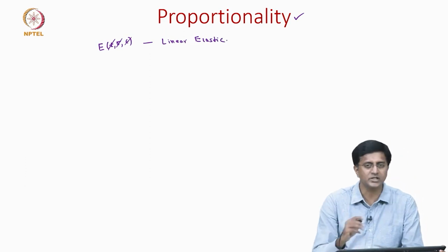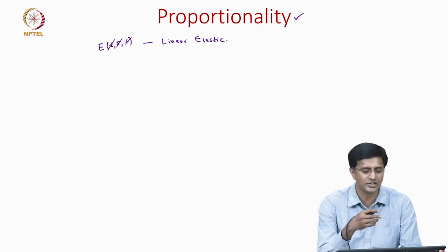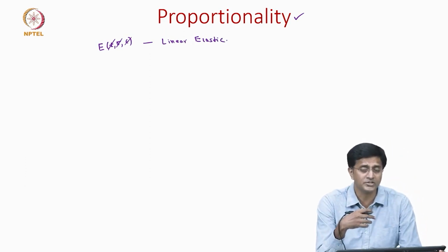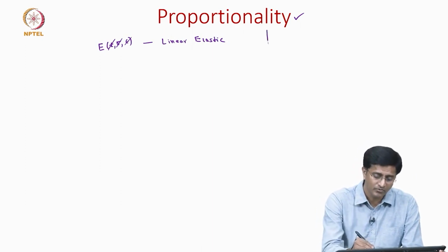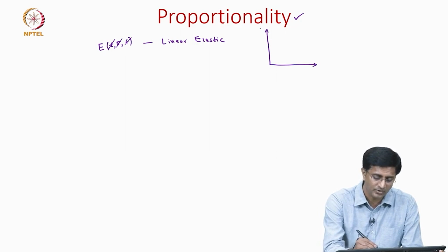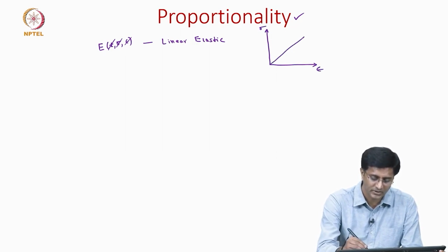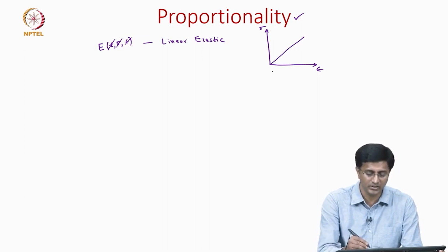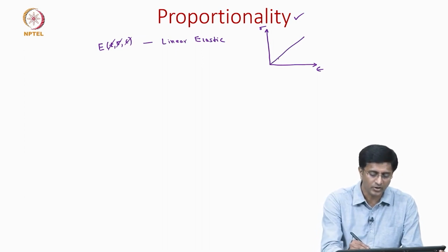For linear elastic, it is neither a function of time, stress or strain. What do I mean by stress or strain? When we look at the stress strain plot and we said this is the response of the linear elastic material, we are only talking about the slope of this curve when we discuss about modulus E.